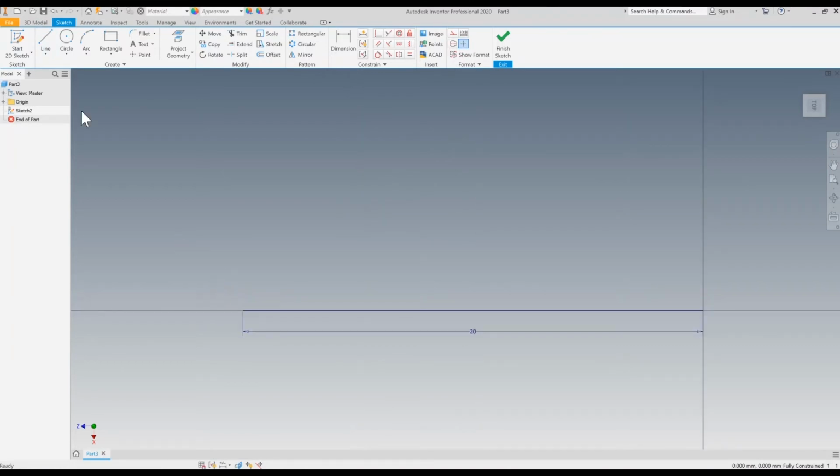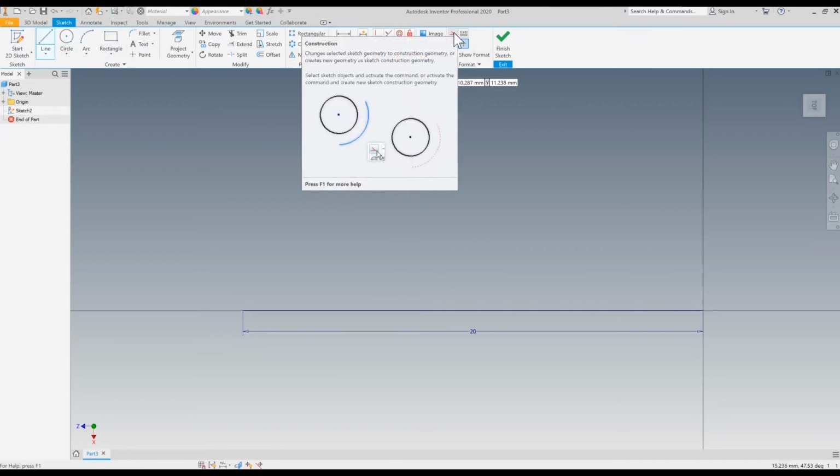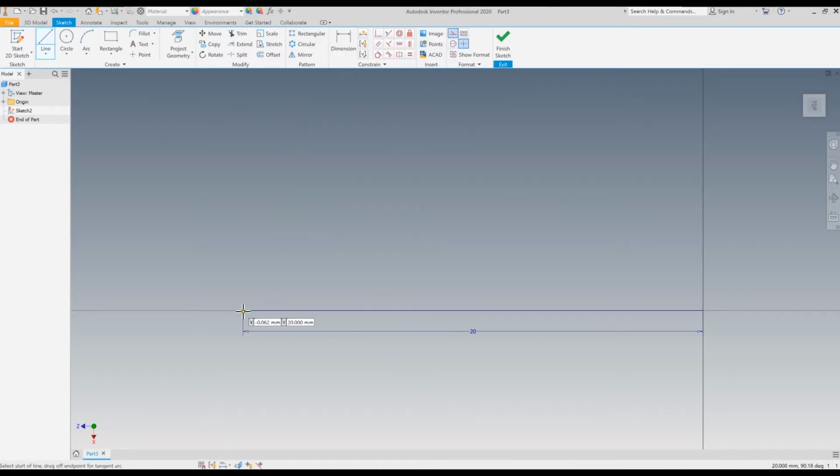So I want to make 3 mm holes. What I'm going to do is use the construction line tool. Here's construction lines here, and I'm going to make the width 3 mm. I'm also going to use the center line tool to create my center line in which the link will be mirrored around later on. The length of this doesn't matter, so I'm just going to set it to anything, as it won't actually be in the final part.